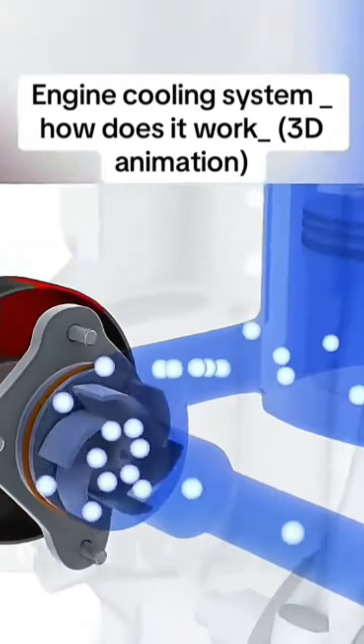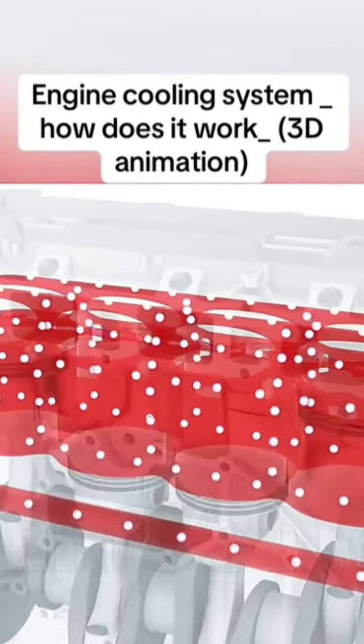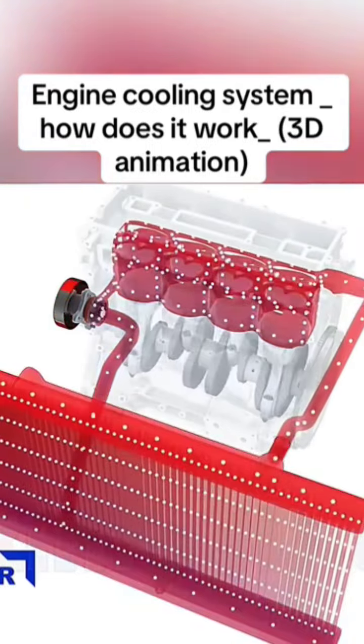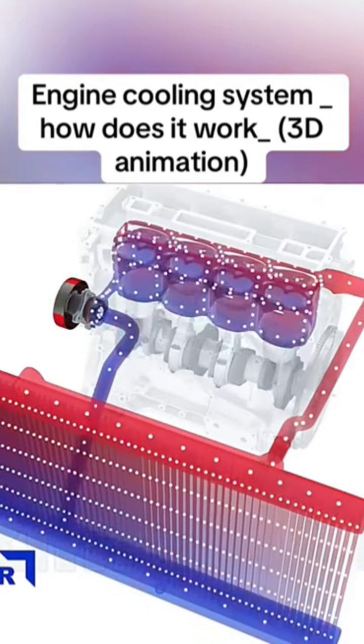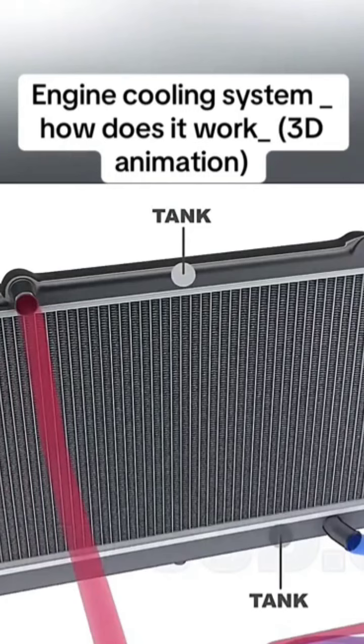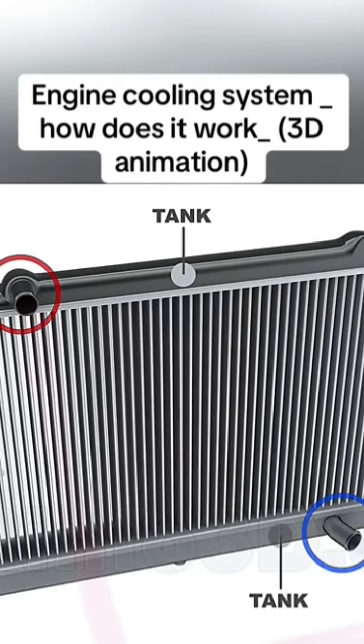The liquid would be cooled too slowly in this setup, causing the engine to overheat. Therefore, the radiator cools liquid through a high-efficiency heat exchange process. The radiator is made up of two tanks with an inlet pipe for heated liquid and an outlet pipe for cooled liquid. The tanks are linked together by a system of tubes.